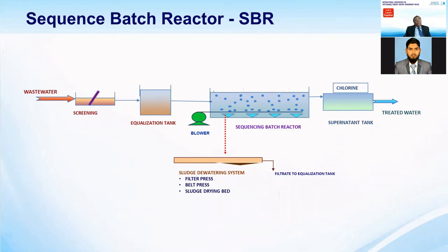Here we put packing material or some filling media which increases the surface area of the tank so that attached growth can be developed. The bacteria developing by decomposition of the BOD and COD can be sustained or retained in the aeration tank by attaching themselves to the media, which gives them a place to stay.